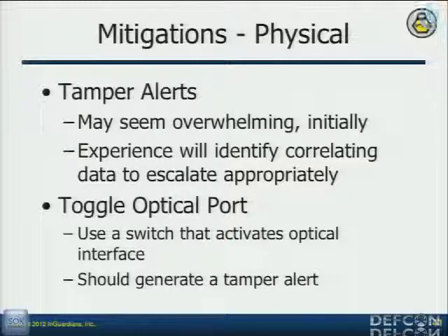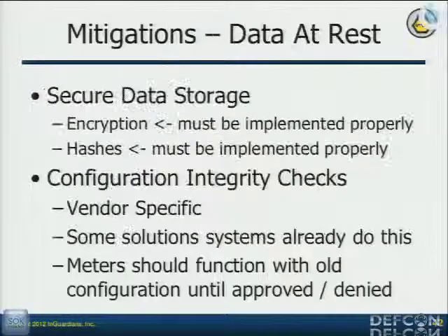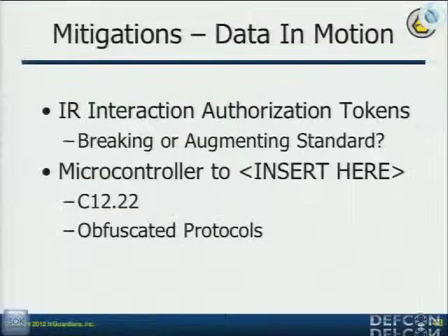Tamper alerts, on the smart meters, maybe not so much because there's so many out there, but definitely on the aggregation points, for the pole tops, you want to do that. Encryption has to be done properly, we all understand that. Configuration integrity checks, we just talked about that.